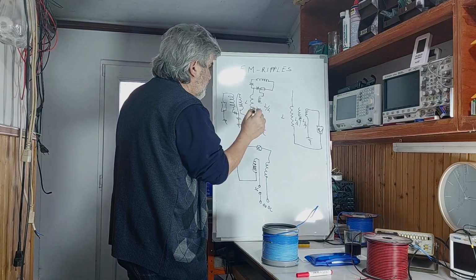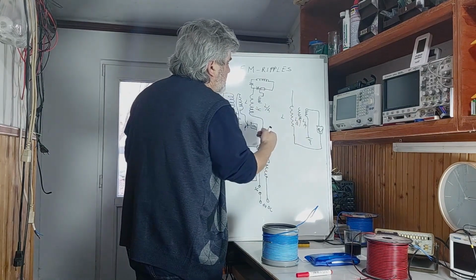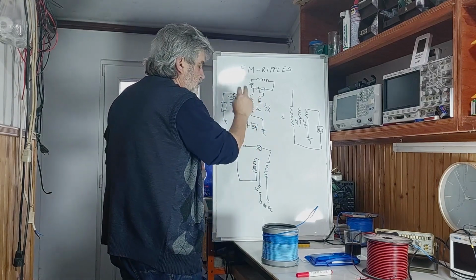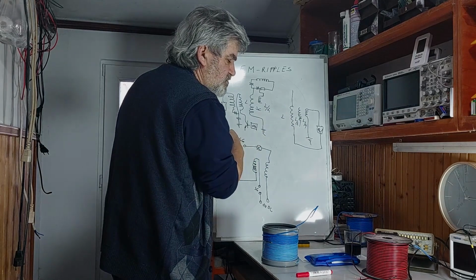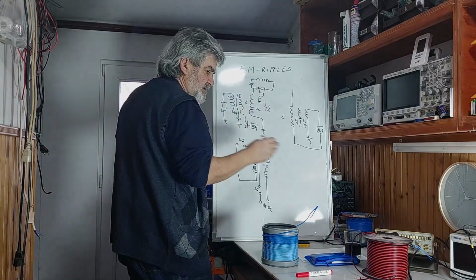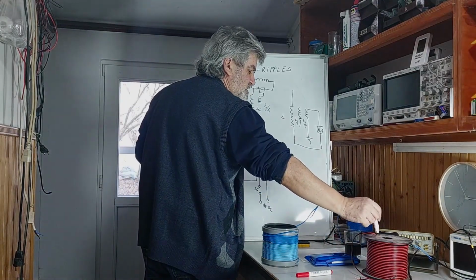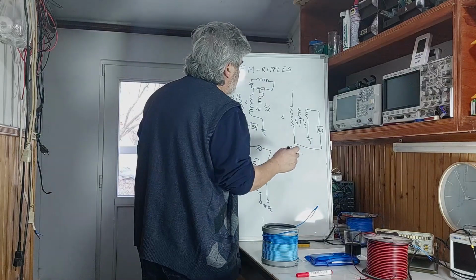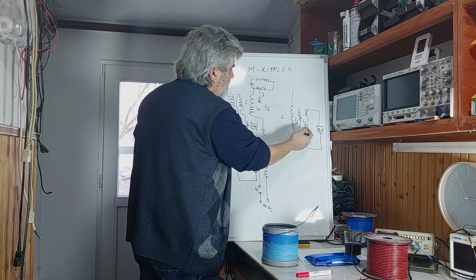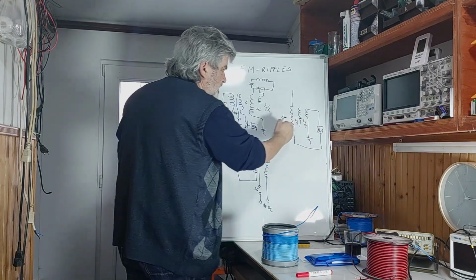And what I found, let's say, if I had several different coils. By the way, when you work with high voltage, high frequency, try if you can to use one layer of the coil, not like this one with many layers, because there is too much parasitic capacitance between, and you will get nothing. So imagine that you have the ratio of 1, 2, 4, but could be any between.